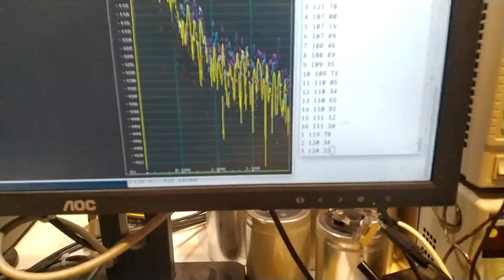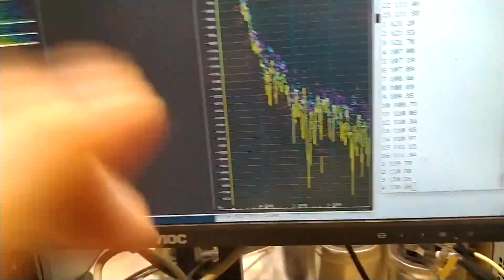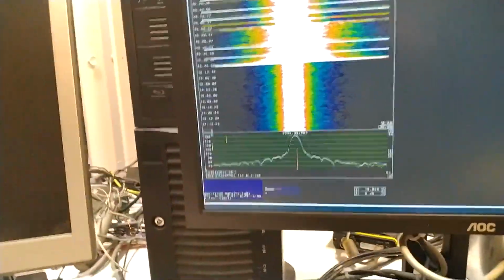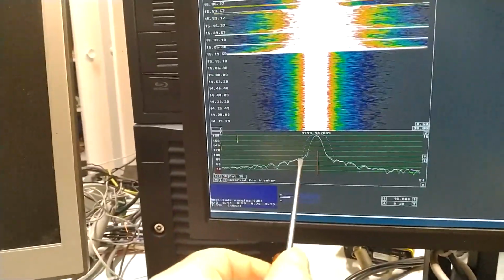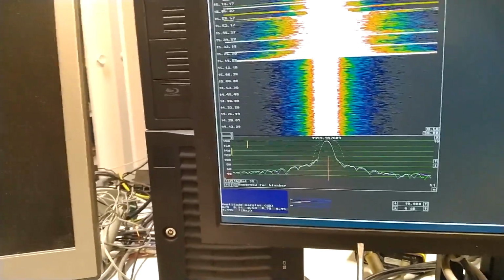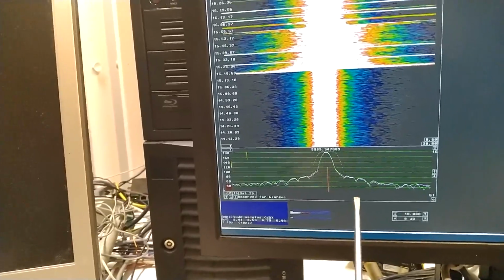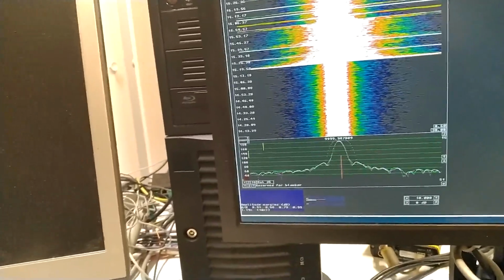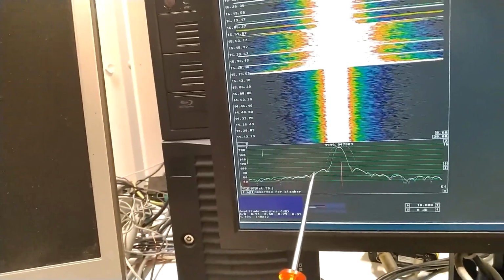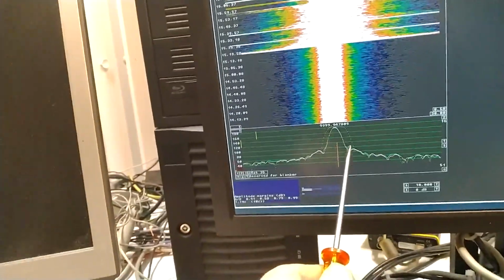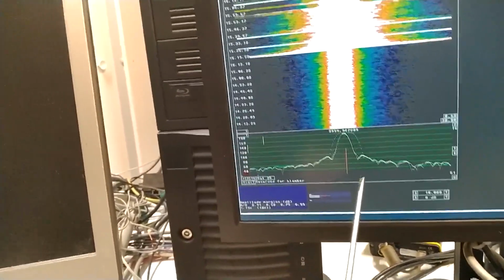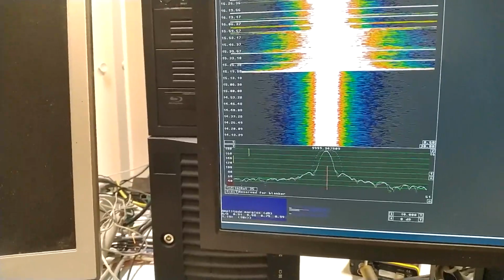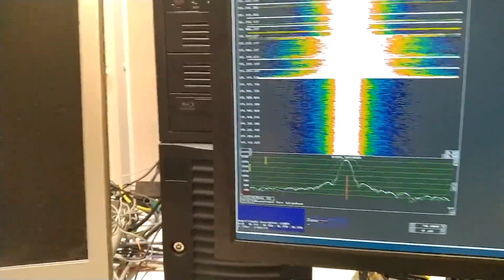The average noise is about 120 now, and the peaks here are gone. What I can see is that the noise very close to the carrier is in the order of 10 decibels stronger now as it was here, but it is only the very closest range. We have these peaks that have the green and the red trace at the same level, meaning all that noise comes from the oscillator, and it's not a result of the correlation.